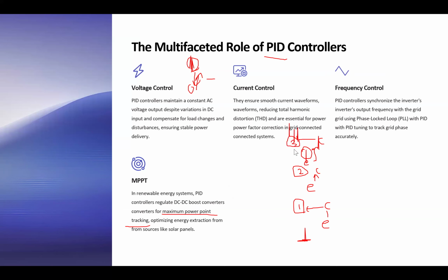Sometimes this happens: we overcorrect, we get a little bit far, and then this feedback goes over and over until we are close enough to our targeted value. Like our fourth step is very close to our targeted value. This is how PID works. This correction value, that proportional integral differential that we talked about, is the process that translates the error to a correction value. How you translate the error to a correction value is the PID situation.